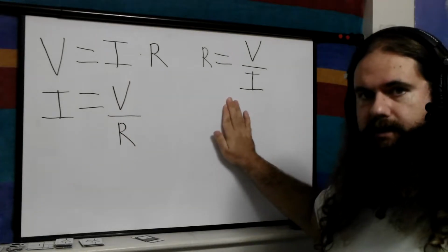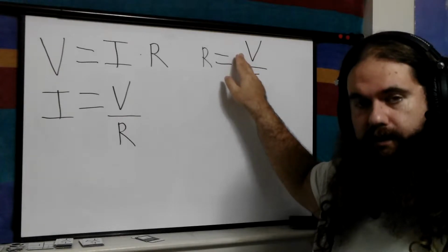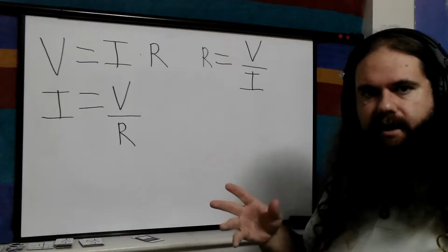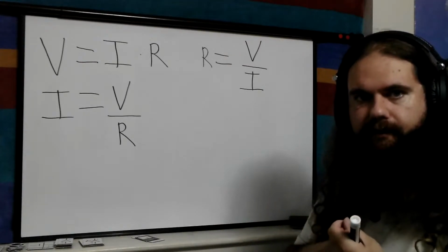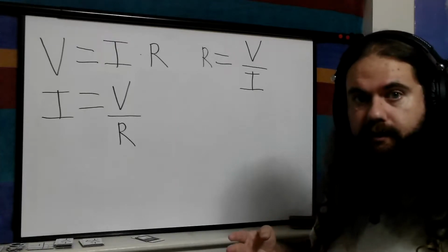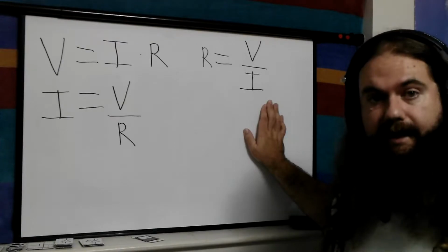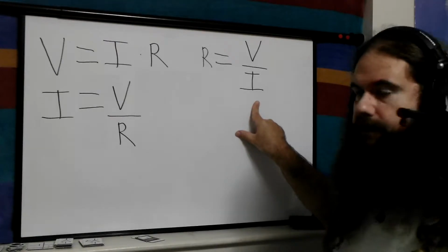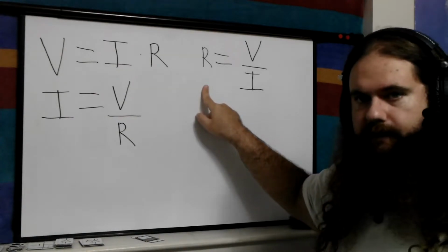This is probably the most common version. You know your input voltage because you know a certain power supply. You know what your other devices need, such as USB input is 5 volts. You might have 3.3 from a power rail in a laptop, that sort of thing. And you also know the current, for example, for an LED. So you know what amount of current you want flowing through that part of the circuit. You're calculating the resistance that you want left over.